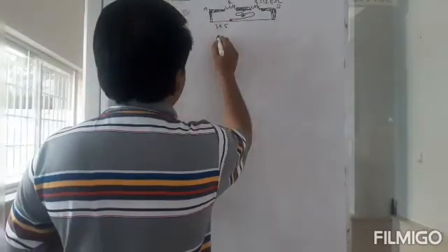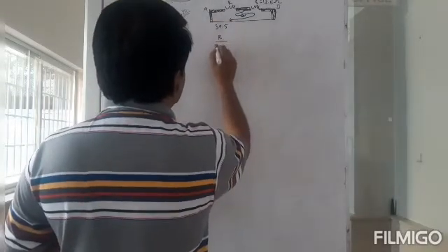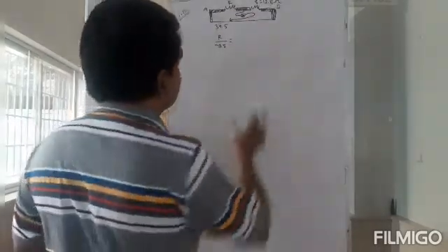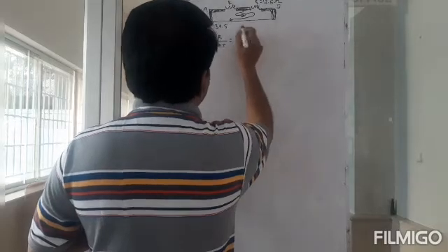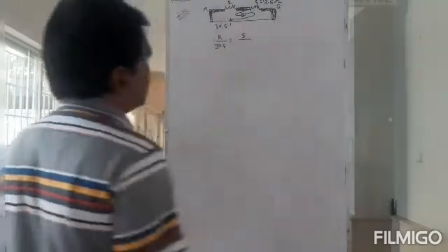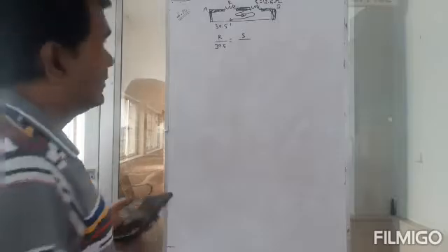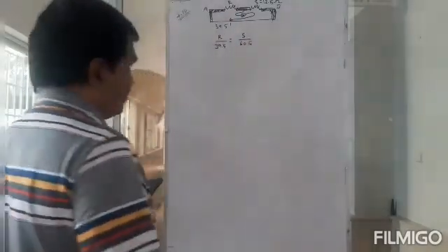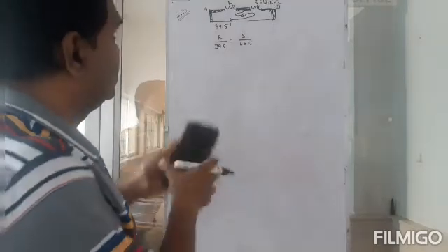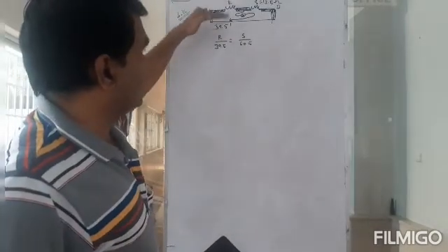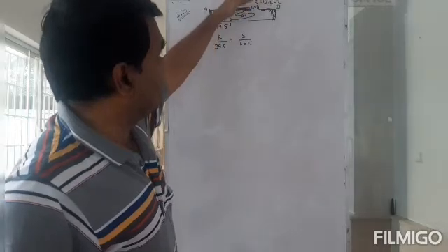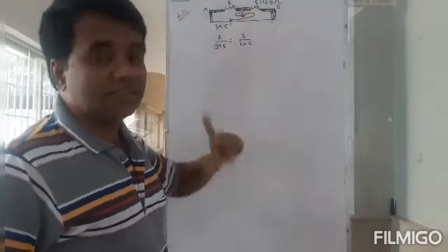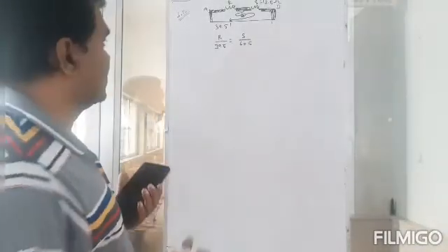So what do we know? We know that by the balancing condition, R by 39.5, R by this resistance equivalent, is equal to S by, what will that be? That is 100 minus 39.5, that is 60.5. So R by this length is equal to S by this length in the balancing condition, correct?